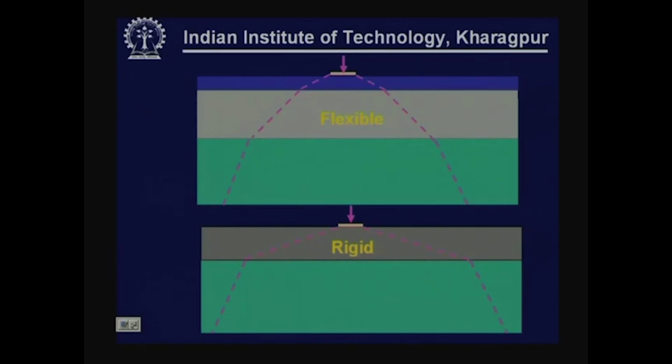Whereas when we consider rigid pavements, most of the load spread is done by the concrete slab. As a result, the foundation does not have much of a role to play in the case of concrete pavements as far as the load spread or load carrying capacity is concerned.